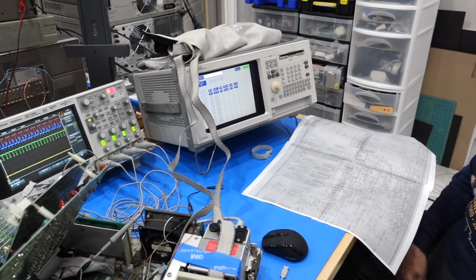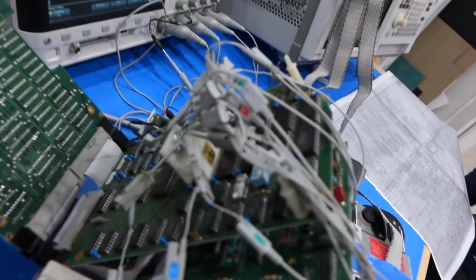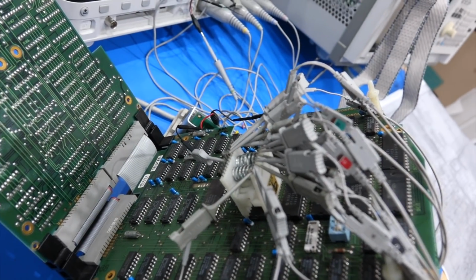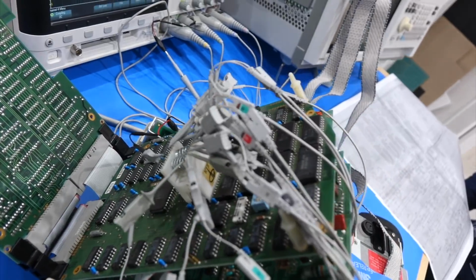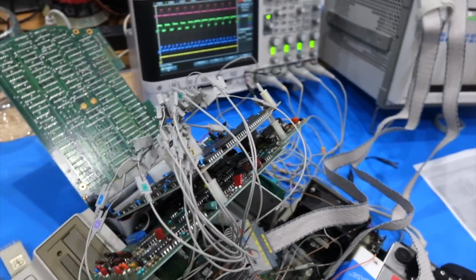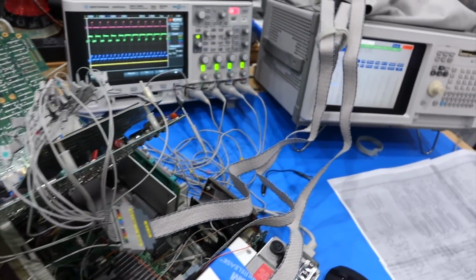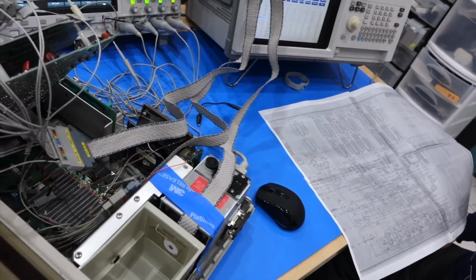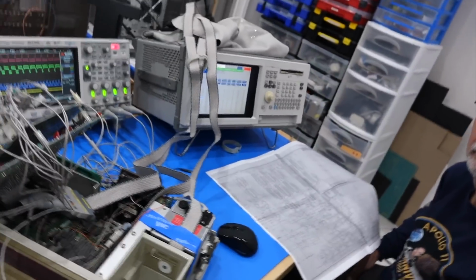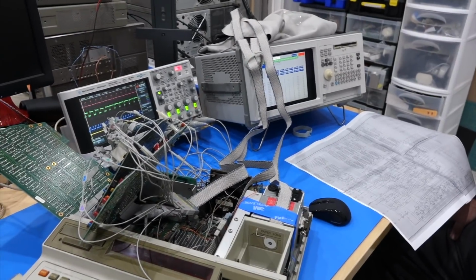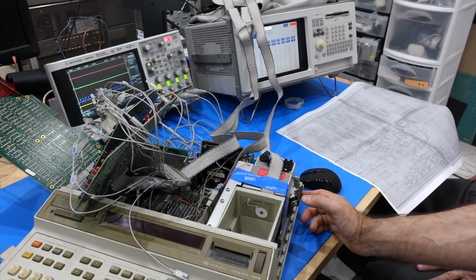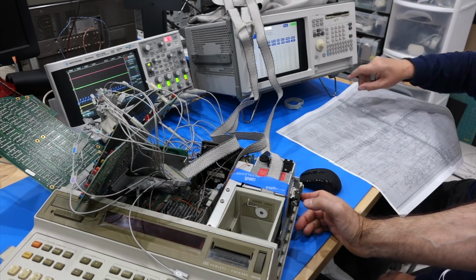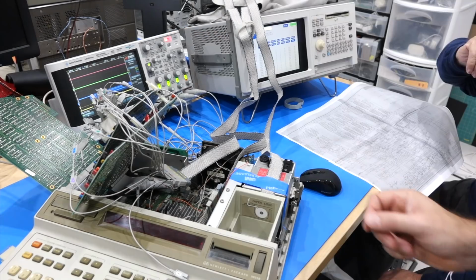So let's get on the data bits and see what happens. All right. So now we're going to look at 8 of the address bits and 8 of the output bits in the ROM to see if the address comes to the chip correctly, which we think it does actually, and if any data comes out, because definitely the processor cannot read any. Okay, got it. Oh, I got nothing. You get anything?